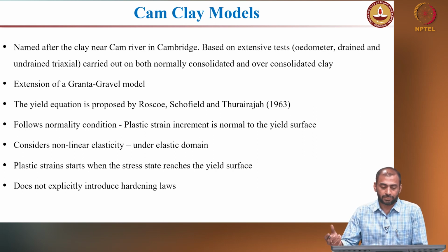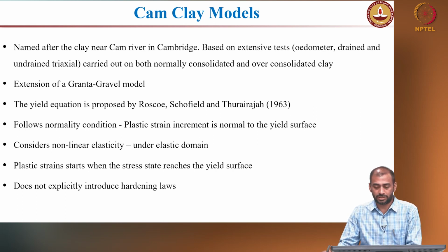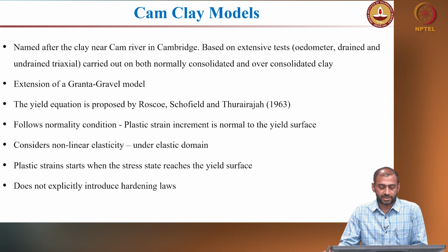The clay from that river was used to perform a lot of conventional tests such as the oedometer test, direct shear, and drained and undrained triaxial tests under both normally consolidated and overconsolidated states. Based on this extensive experimental study on this particular clay, they came up with the Cam-clay model.